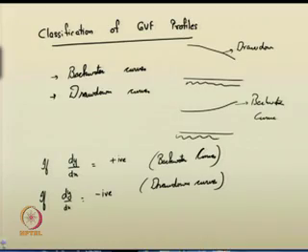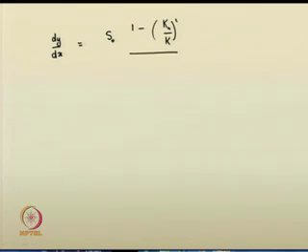So, what are the conditions now? Look into the dynamic equation, dy by dx is equal to S 0 into (1 minus (k n by k) whole squared) by (1 minus (z c by z) whole squared). This is your dynamic equation using conveyance factors and section factors.